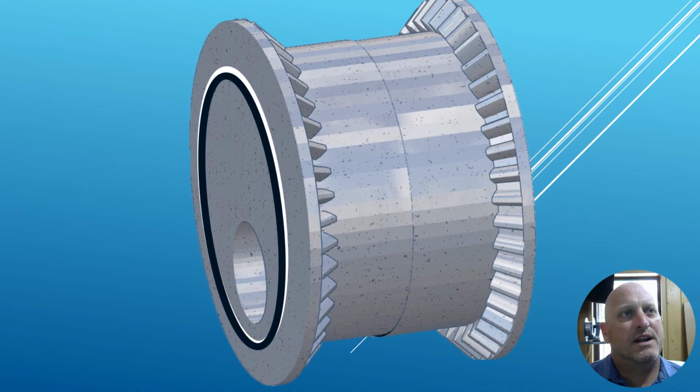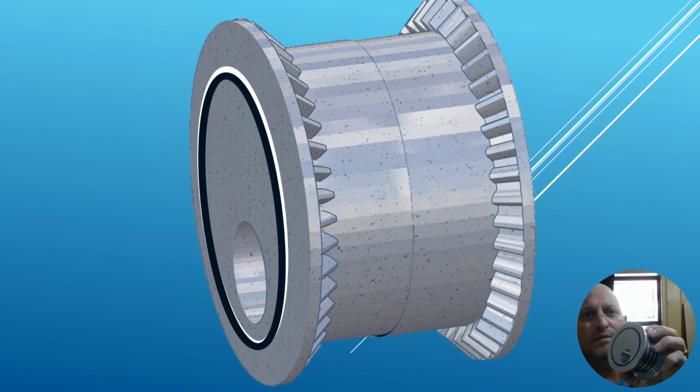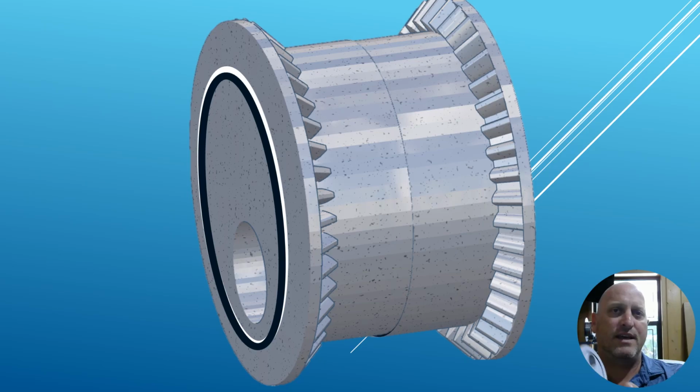and I know a lot of you are thinking, well, how does it seal? So first and foremost, I wanted it very simple to seal and inexpensive. So we can use off-the-shelf standard O-rings. And what it looks like from a perspective, you just have a channel that holds the O-ring into place. And then that way, once it goes onto the interior surface of the body of the valve, that seals that part. In addition, you have O-rings in between here, and it's difficult to see from this picture, but you've got